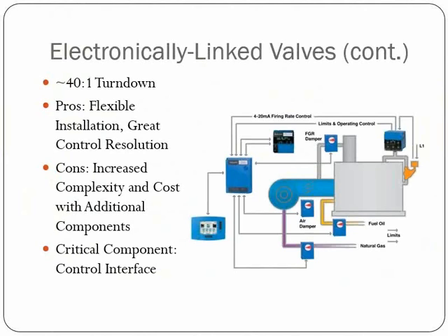The cons are that now we've got additional electrical components that we're adding into our control system, so there's some complexity there. You would have to add interlocks into your control panel to ensure that everything is okay from the air-fuel ratio standpoint, which we didn't have before. And then there are some associated costs, of course, with the additional components.